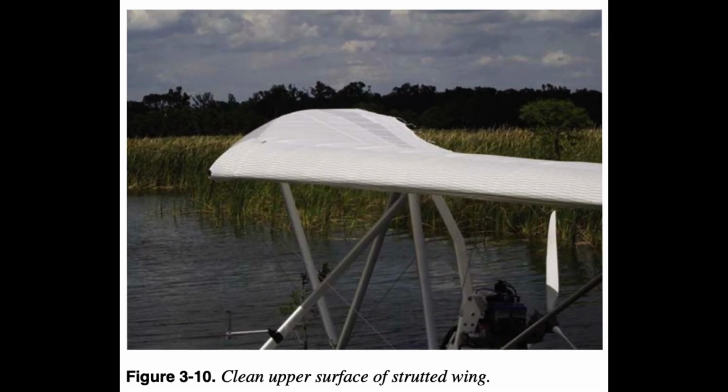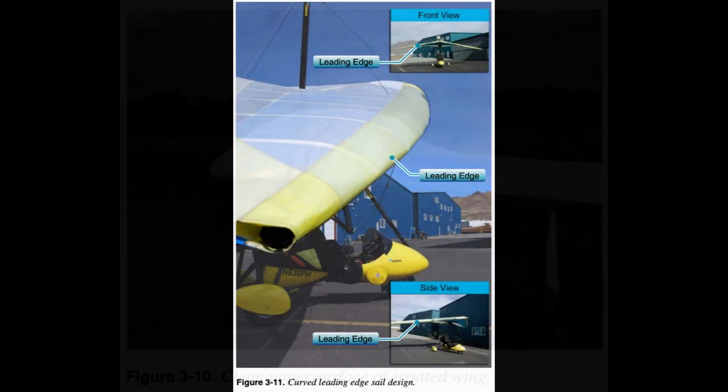Strutted wings have a clean upper surface with no holes required for the king post or wires to go through the top of the sail. This reduces interference drag on the top of the wing, increasing overall efficiency. No holes in the sail also eliminates any high pressure leakage from underneath the wing getting sucked up to the lower pressure on top of the wing. Figure 3-10.